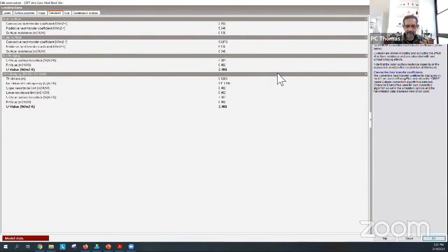Okay, and sometimes it's only a convention, but in some countries, like in Australia, we will use R values for opaque construction and U values for window construction. You don't do that in India. In India, you generally use U values for everything. So just be aware of that. Okay. Now, there's an interesting one here.